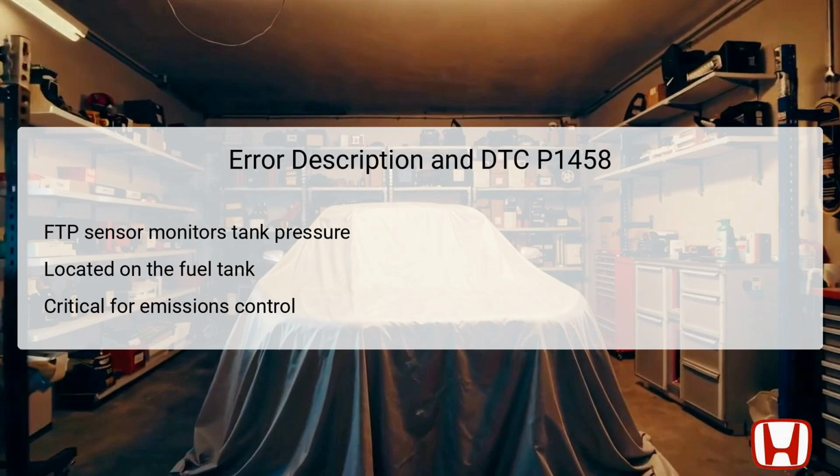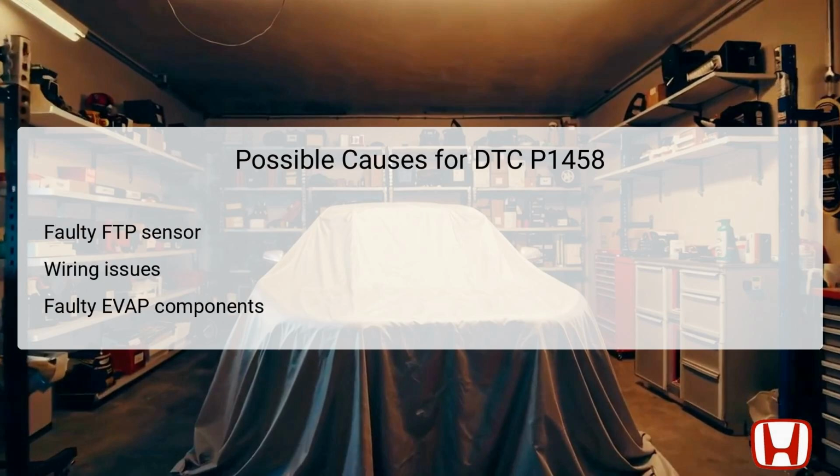If this sensor fails or provides inaccurate readings, other components may also be affected, such as the EVAP canister vent shut valve. Thus, understanding its role and diagnostic importance is essential for effective repair. Diagnosing DTC P1458 involves considering several possible causes.